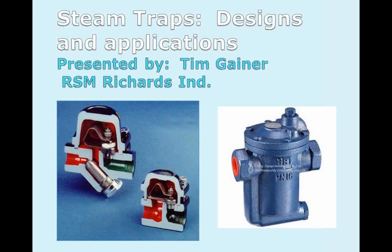That's one of the fallacies I've run into several times. People think they need a gigantic trap on a steam main because it's 12 inches or something like that, and there's not a whole lot of condensate generated on a steam main. You might have high pressure, but they can be small traps because the discharge volume is relatively small.